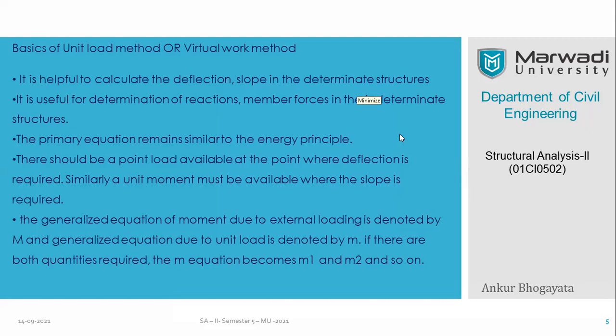As we all have listened to Stephen just now, what he said is that definitely a point load targets a point, and you know that deflection is related to a specific point also, right? So that's why we ideally select a point load to obtain the effect of, or to symbolize, the deflection in the member. That is the ideal load type to be used. That is the first thing. Since point load is associated with deflection, and deflection takes place at a specific location. And if you use the UDL, you are not certain about the location of the deflection, right?